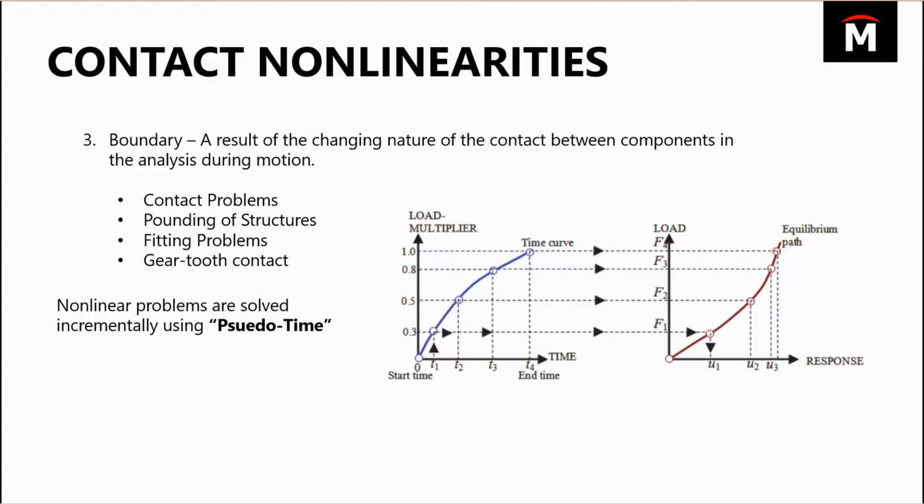So I want to introduce the concept of pseudo time. We might say that a nonlinear analysis happens from 0 to 10 seconds, but those seconds, they're not really the wall clock time. We could just call them pseudo time. In this way, we could say, all right, in 1 second, let's put on 10% of the load. And we can measure the response there, the displacement after 10% loading, and say, okay, now based on that, maybe the direction of our load needs to change because something's bent a whole lot.